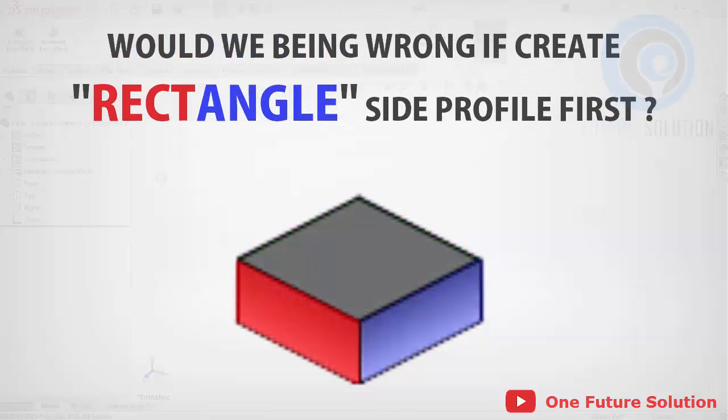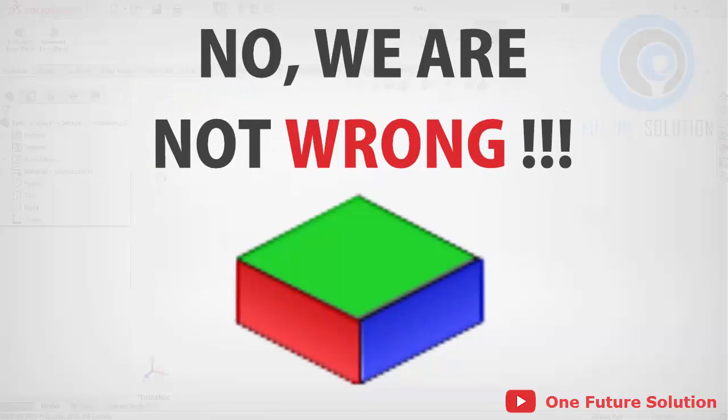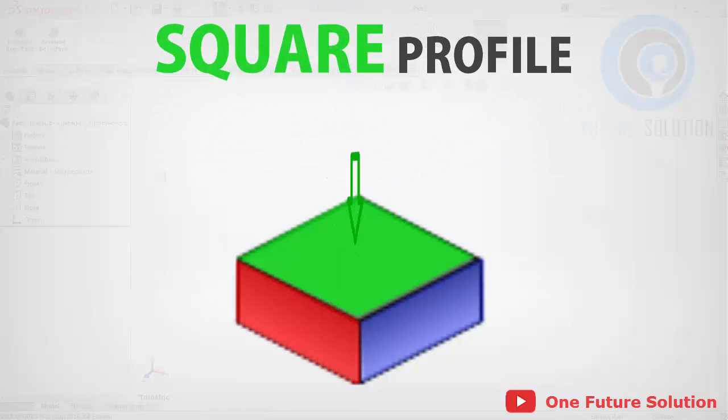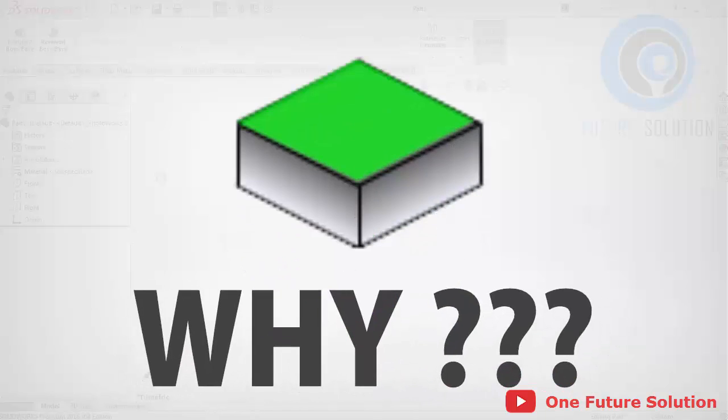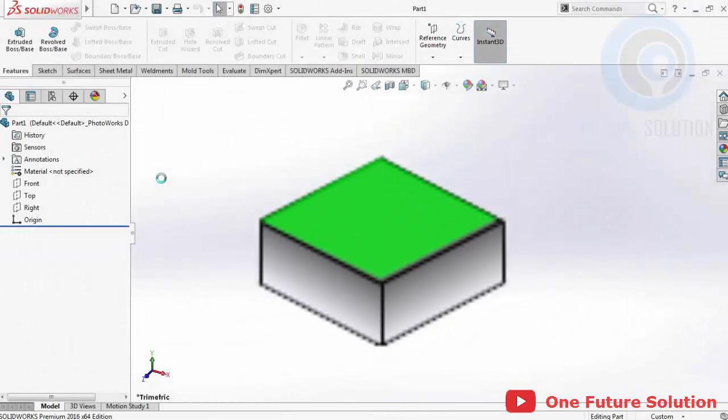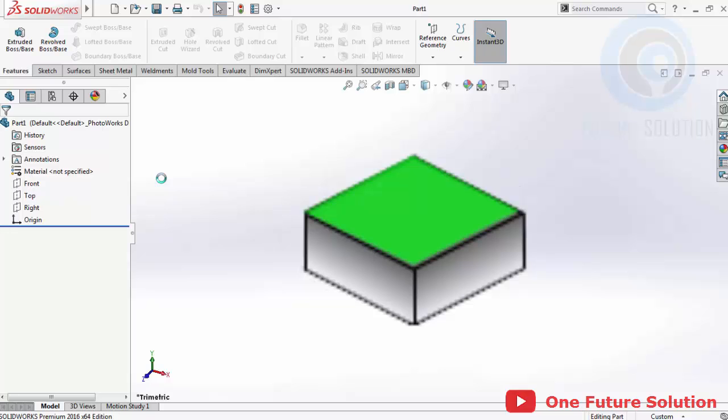But would we be wrong if we create the side thickness rectangle profile first, then extrude it to get the wide geometry? No, we're not wrong, but it's better to use the square main profile than the rectangle side profile as the first sketch profile. Why? This will help us in the future if we modify this model. It's easier if we work with the square profile as the main or base sketch.